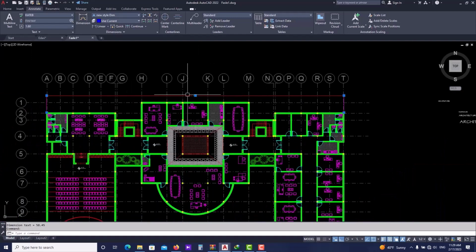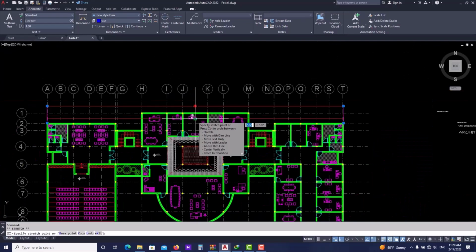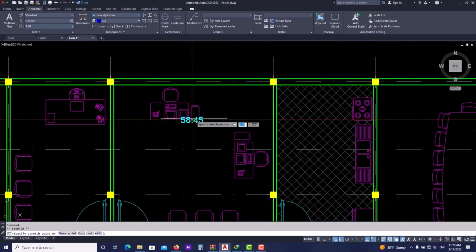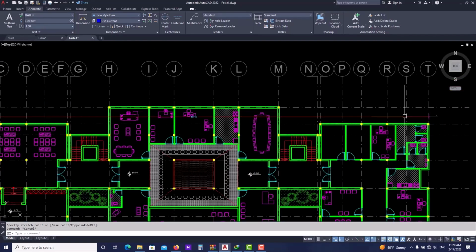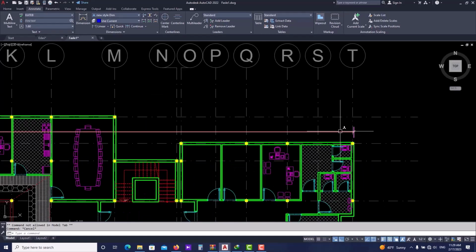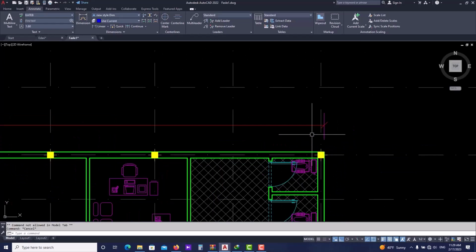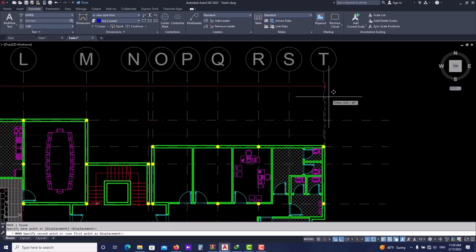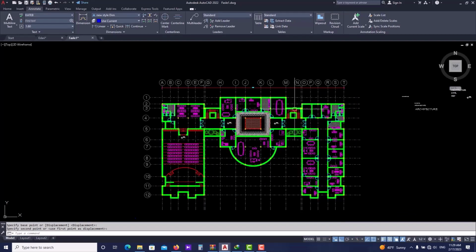Yeah, it's actually okay. Now to reduce the length of the extension line, you can set this here, and then you can move this up, or you can actually deactivate your extension line completely. But let me just type enter and move the dimension up like this.